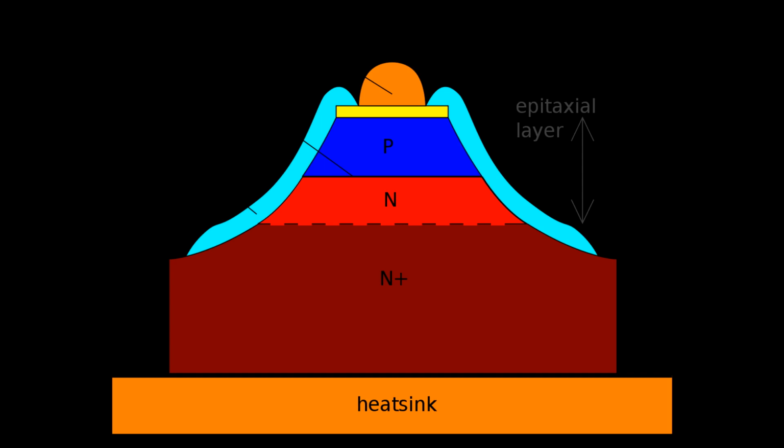6. Demodulation. Demodulation is the process of extracting the original modulating signal from a modulated carrier signal. In FM, this involves recovering the original audio or data signal from the frequency-modulated carrier signal. 7. Advantages of FM. FM is less susceptible to amplitude variations due to noise, making it more resilient in noisy environments compared to amplitude modulation, AM. FM offers better audio quality and fidelity, making it suitable for high-quality sound transmission in broadcasting. FM is less affected by electromagnetic interference and fading effects compared to AM.